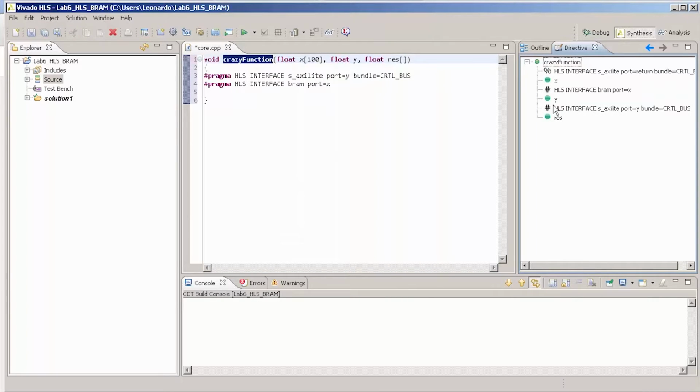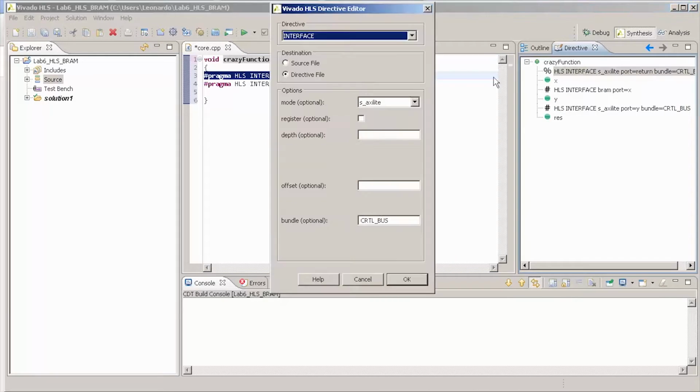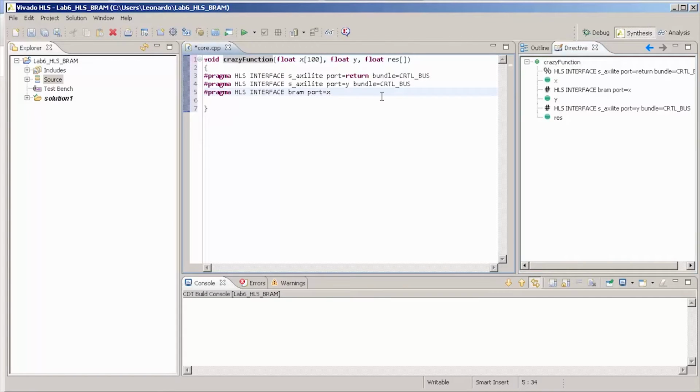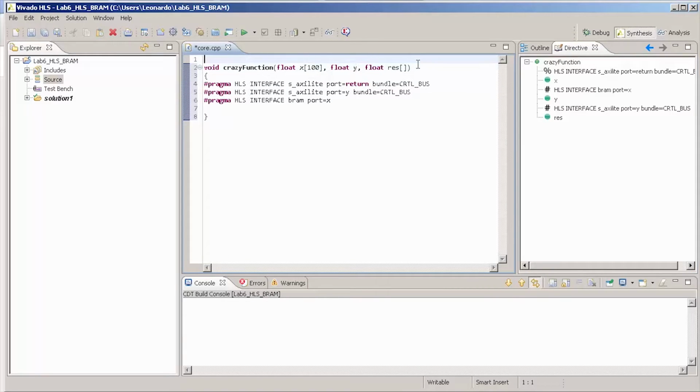We're going to see this after we finish this IP and test and verify that everything is okay. In Vivado, we are going to use a dual port BRAM, and one of the ports will be used by the IP core to write or read the results, and the other one will be used by you to input values in this RAM, or output values as well.